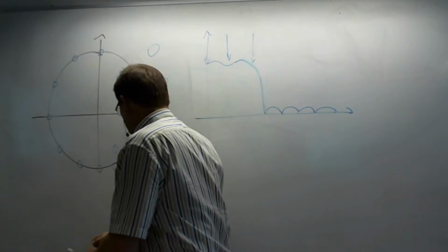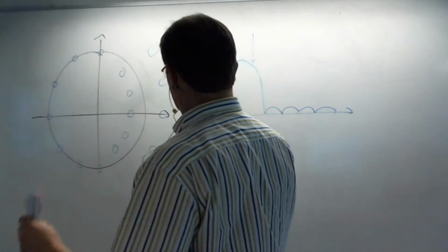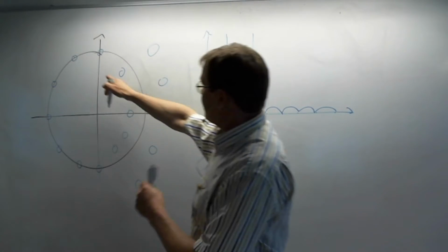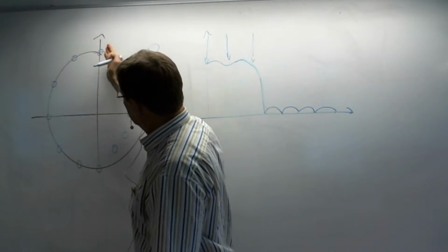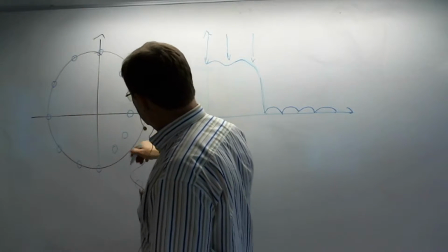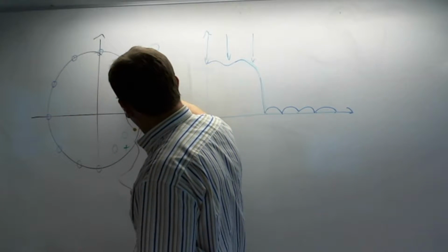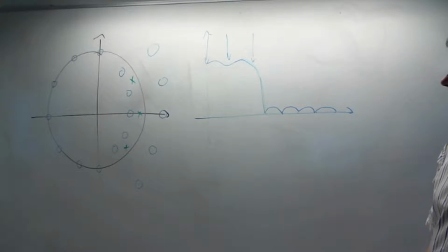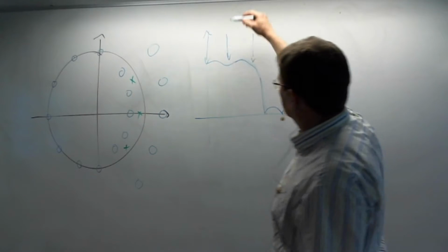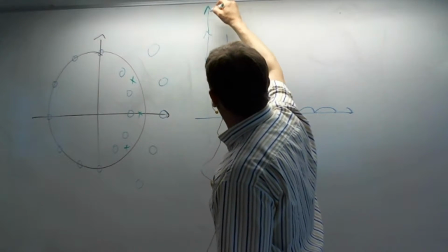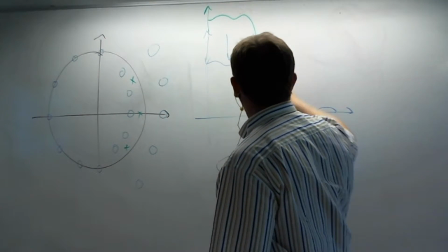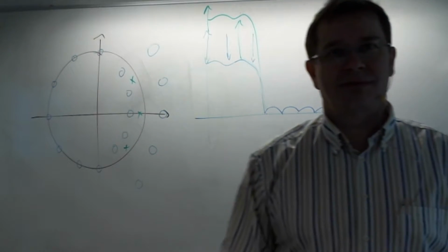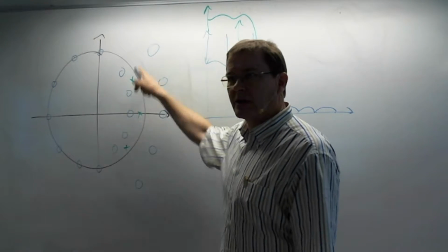Anyway, when you take the opposite way on the passband, you can still have the same stop band notches there, but, for example, put only a couple of poles close to the unit circle, so you get more gain, but at the same time better stop band attenuation with fewer calculation points.